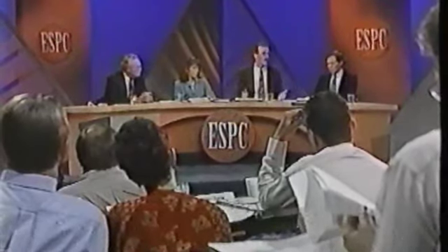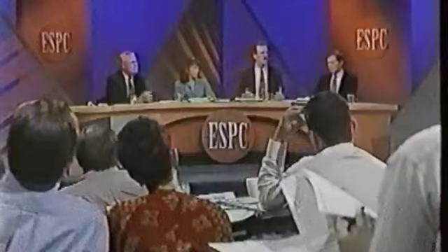We looked into it. First thing, when you see there's no savings, you've got to examine what's the cause. And it turned out they added 20% square footage. They've been doing reconstruction at that site. So from a utility bill perspective, there was no savings. But when we went in and did the option A approach to the lighting, it was clear that the lighting energy savings was being achieved. So you really have to examine and find what the fault is and research it.